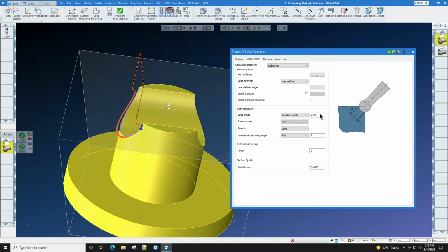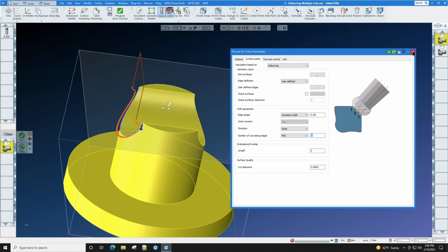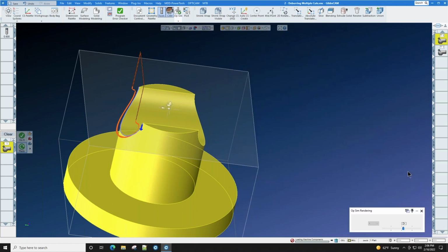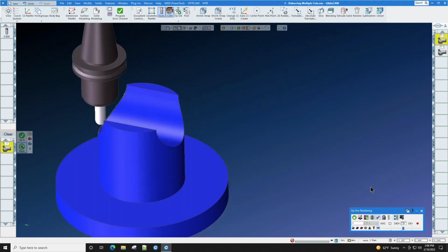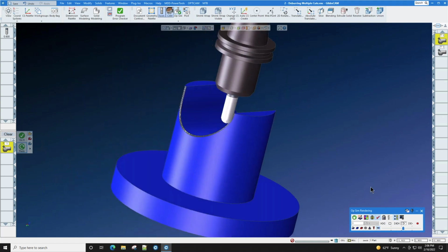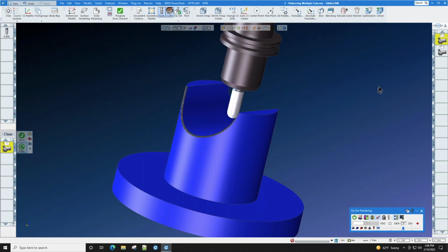We set the width, and now not only can we deburr this in multiple steps along that shape, we can deburr it now not only with a lollipop tool, but with a ball end mill and a flat end mill. Let's have a look at the first toolpath that we have here. Let's look at toolpath 1. We're going to use skip unselected ops and just run toolpath number 1. We're running this in 3-axis mode because, again, the 5-axis module works on 3, 4, and 5-axis machines.